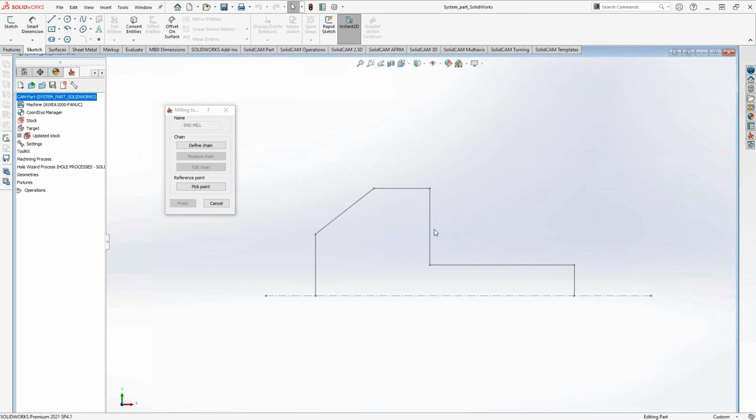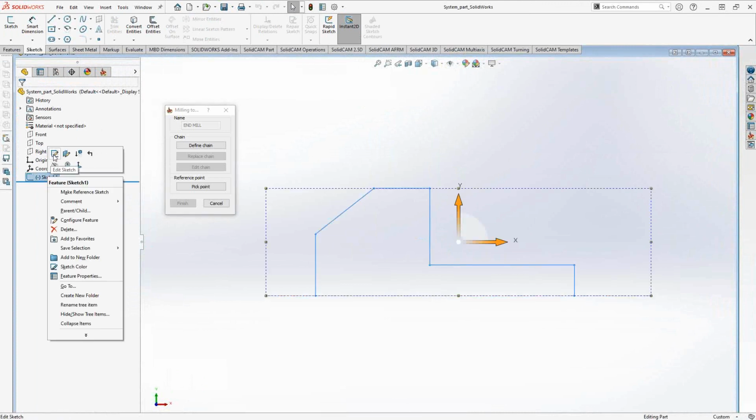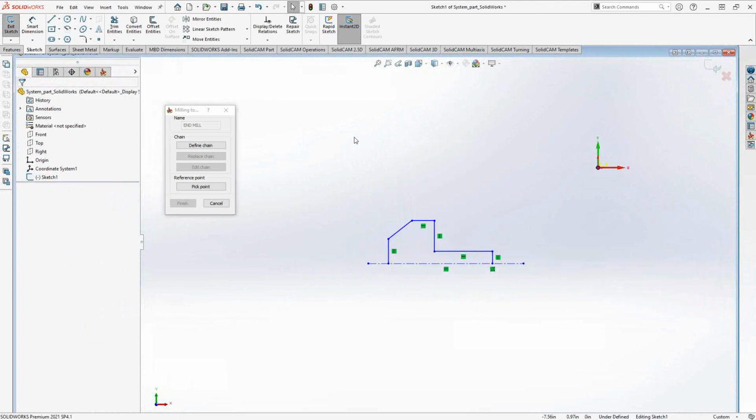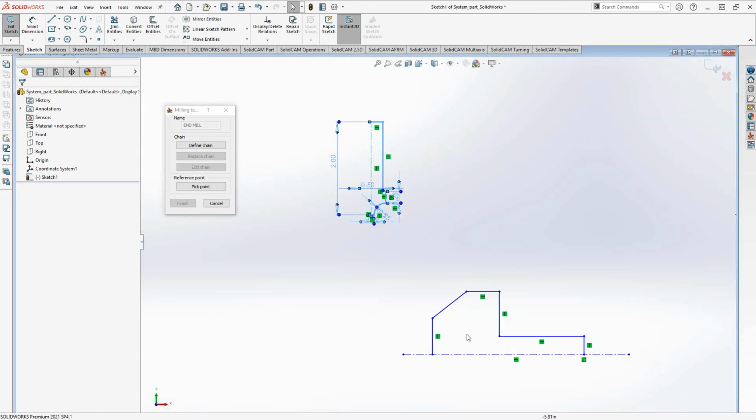We'll go back to our SolidCAM template. Here, I'm actually going to take a look at the template itself, and there's a sketch in here as well. I'm going to manipulate this sketch. So before we even do anything inside SolidCAM, we're just going to manipulate this sketch to essentially include the sketch that I just created. So again, opening up the sketch for editing, you can see it's highlighted in blue, indicating that we're inside the sketch. On my keyboard, I will click Control-V as in Victor, importing my sketch. So I'm just going to place this in the proper position here so that I can define it as my shape tool. So again, the functionality here is not that different than the shape tool functionality, but we're going to do this specifically for a corner round.